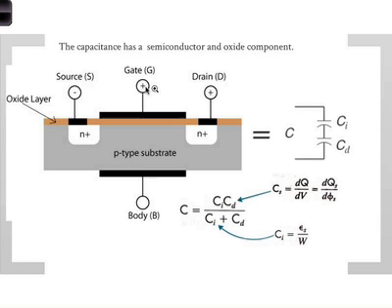So the capacitance we are talking about is looking from the gate. So you expect some capacitance from the oxide, and you expect some capacitance from the semiconductor. And indeed, that's how you model it in a device. So you have a CI, which is the oxide capacitance, which we just talked about. And then you have a CD, which is depletion capacitance coming from the semiconductor. Okay, and they're connected in series, as expected. Okay, so it's easy to understand. The analogy is straightforward.